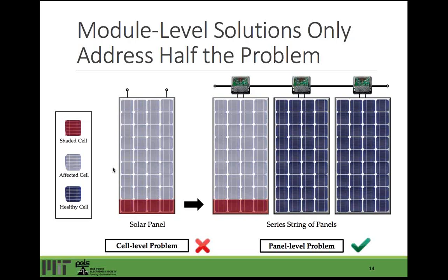With maximum power point tracking scaled to the cell level granularity, every cell, rather than panel, can operate at its respective maximum power. So it can recover all the power loss from the unshaded cells inside the shaded panel, and thereby significantly boost the overall power extraction. In addition, if we were to manage the cell voltage correctly, we can also eliminate the hotspot problem at the same time. So this is what our goal is.